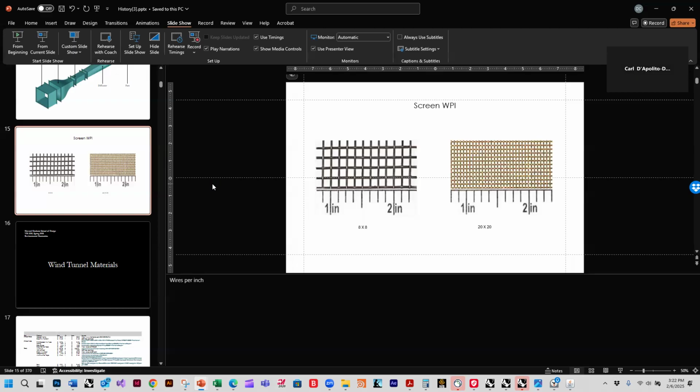If we can't take it out, we'll just rivet it in because that'll be easy. We can use blind rivets so we won't have to reach our hands in the fan and it'll be easy to attach permanently. The other option is we could make little hooks on the fan and have little claws on the tube.